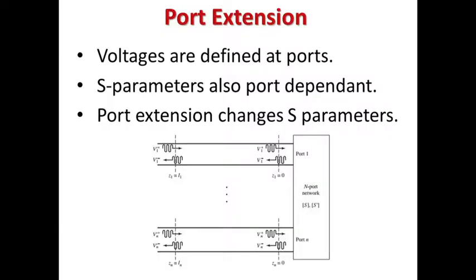Similar thing here. Now, one thing that we have seen in the first lecture today, that in general for microwave frequency with waveguide type of things, we cannot define voltage uniquely, but under certain restrictions we have defined. But that definition, we said at that time, is only at a particular terminal plane, at a particular port I can define uniquely a voltage or current.